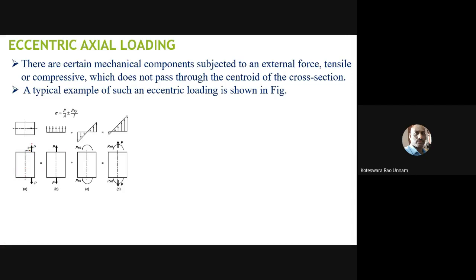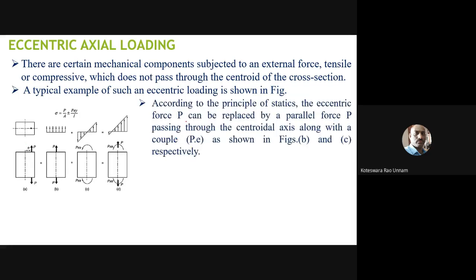If I transfer this load from one plane to another plane, I think you might have studied this in engineering mechanics itself. If you want to transfer the force from one plane to another plane, the net effect will be the same load in the same direction plus a moment, given by the force multiplied by the offset distance. That is the principle here. According to the principle of statics, the eccentric force P can be replaced by a parallel force P. So now this is the force.